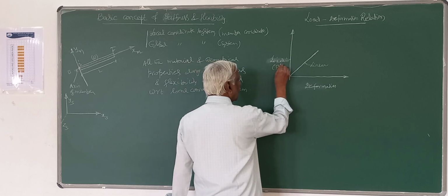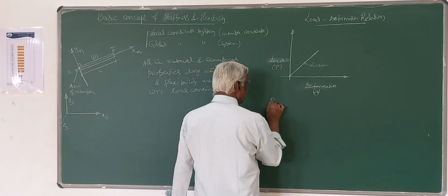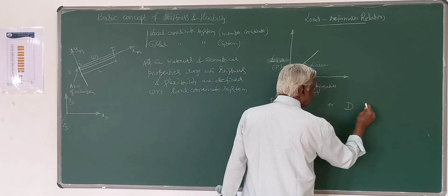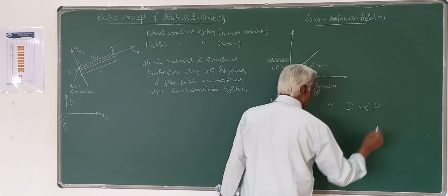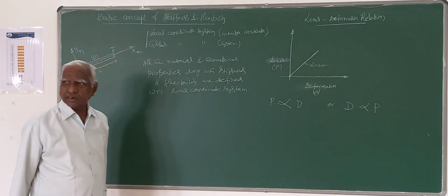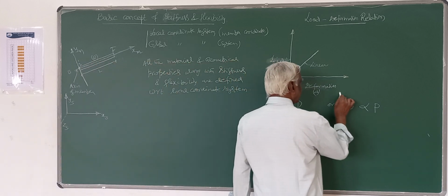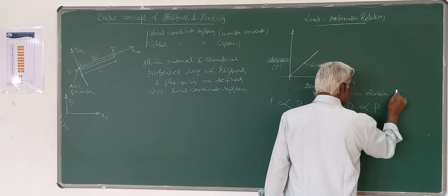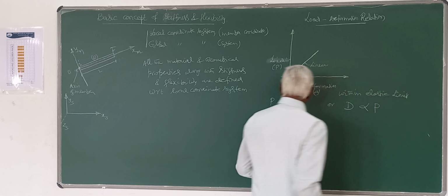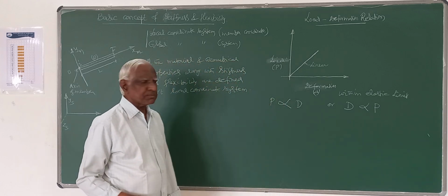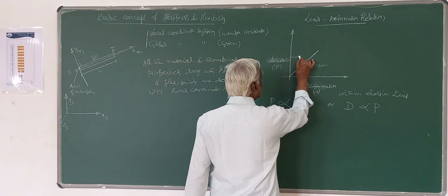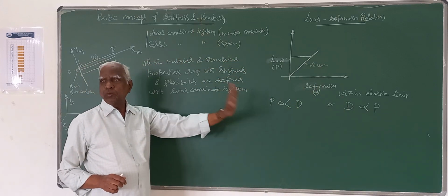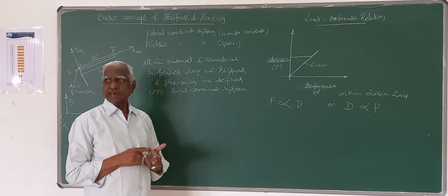That is, this load P is directly proportional to displacement, or you can say deflection, or deformation is directly proportional to load. That is within elastic limit. Within elastic limit, this load is proportional to displacement. And remember, always all our analysis we do within the linear elastic domain.